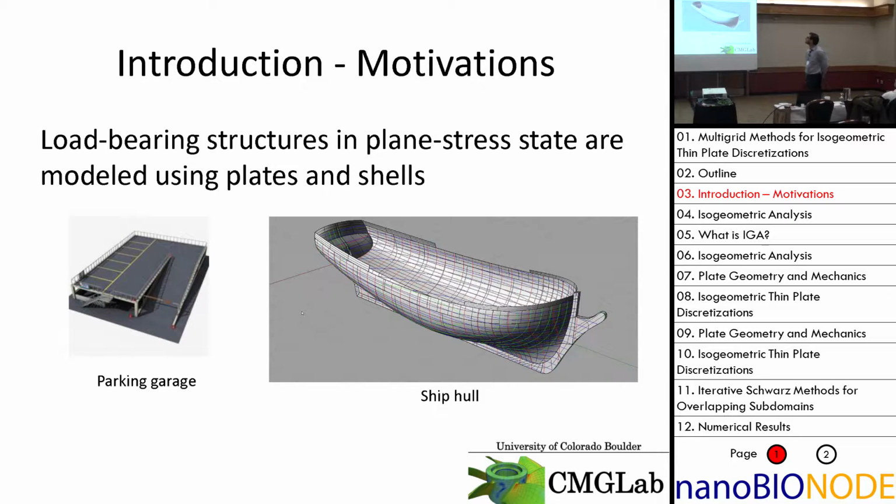So what is a plate? A plate is a load-bearing structure that's in what's called plane stress. So essentially what that is we have something that's flat, and it's loaded from the top, and it will deform accordingly. So that could be things like a parking garage here. You know, cars are loaded, and the levels represent plates, the different floors. Buildings are also plates. A similar topic is a shell, which is a generalization of a plate because it has curvature. In this talk, we're going to just cover and focus on plates themselves, though.